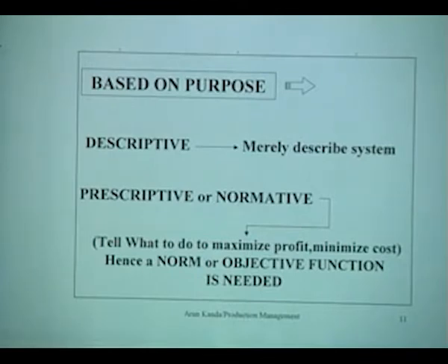For instance, if you were to find out at a traffic light what should be the duration that the traffic light should be on or off, a simple traffic light, and you collect the distribution of the arriving cars and other vehicles, and suppose you do this exercise for a stoppage time of 2 minutes and then 3 minutes and then 4 minutes in your computer, then for each case you would get different average waiting times for the waiting cars.